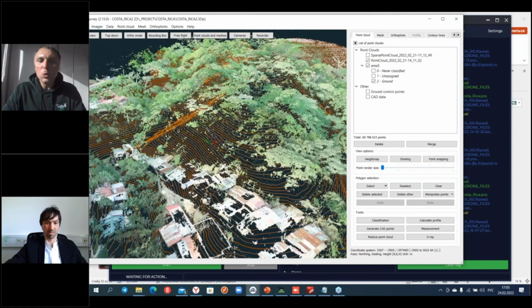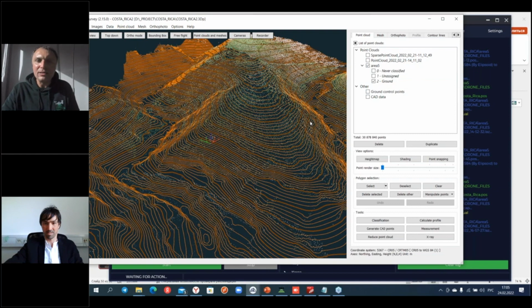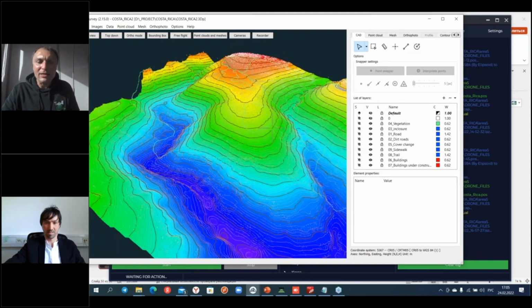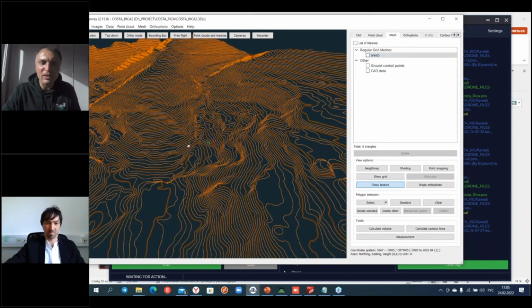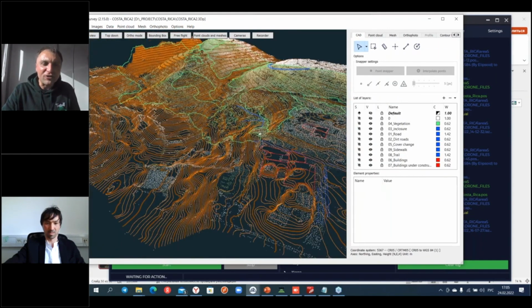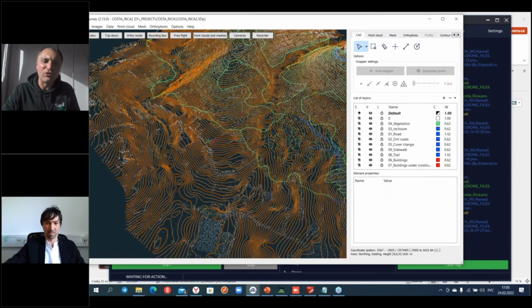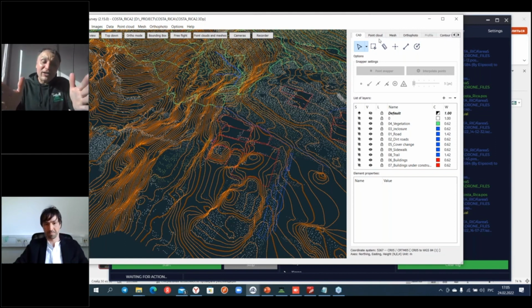After that, we can vectorize point clouds together, and we can create not only contour lines, we can vectorize the data set, and we can create cut data. And this one is cut data, which was created by me within a few minutes. We can open the cut data, and we can vectorize it here, like three-dimensional cut data, like the border of the forest, like buildings here. And of course, you can use the advantages of 3Dsurvey, where you have a lot of CAD functions, where you have an X-ray, where you can vectorize walls of the buildings without any problems.